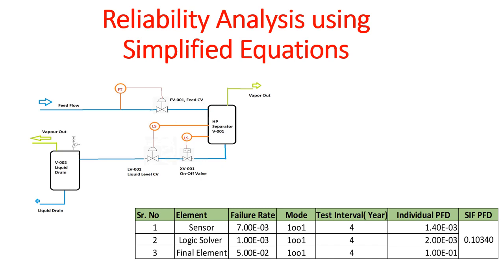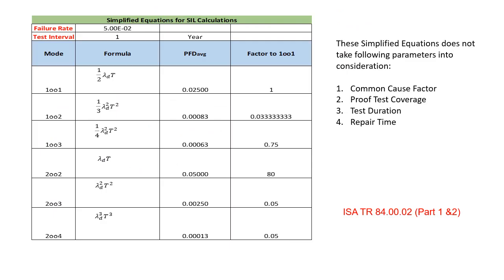In this particular lecture, we are going to take the same example with which we have done HAZOP, with which we have done LOPA, with which we have developed the SRS. We have designed the SIF. Now it is time to analyze the SIF, calculate the reliability of the SIF, and calculate the PFD average of that particular SIF. So let's begin with it.